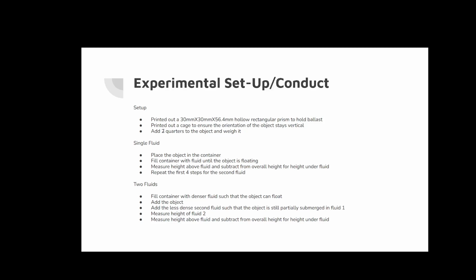It was 25.23 grams, I believe. So we take an object of this mass and we place it in a container. From there, we're going to fill it with fluid until the object can float, and then we're going to measure the height of the object that is above the water. Using that, we can subtract it from the known total height of the object to find the height that is underwater.